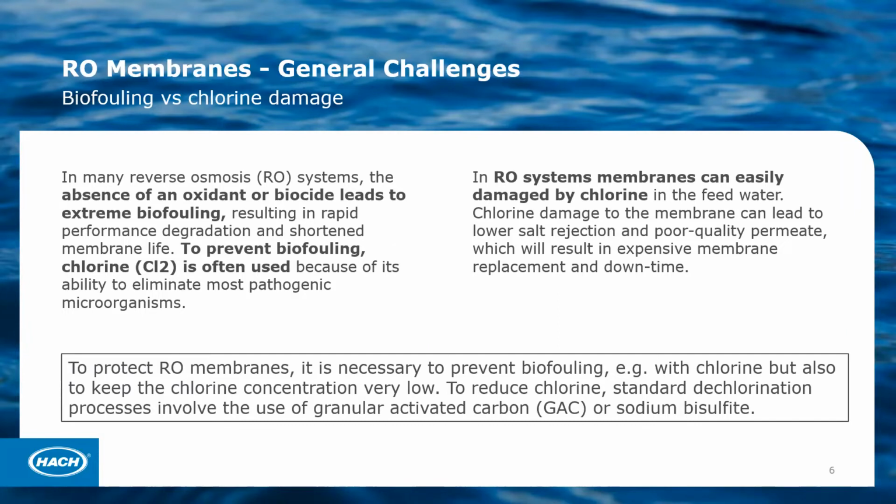So that poses one challenge. We need to remove oxidants from our processed water, our feed water going into our reverse osmosis membranes. The counter to that, though, is when we remove oxidants and we remove any disinfectant residual, we leave our reverse osmosis membranes vulnerable to bacterial growth. We leave them vulnerable to what we refer to typically as biofouling.